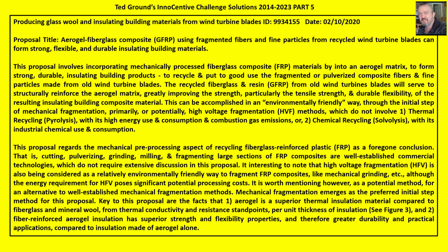So one way to recycle that useful fiberglass material is to first pulverize the composite fibers and fine particles made from old wind turbine blades, and then to use that to make a fairly strong, resilient, and durable insulation material, wherein the fiberglass particles and fibers from the pulverized result of recycling can reinforce an aerogel matrix.